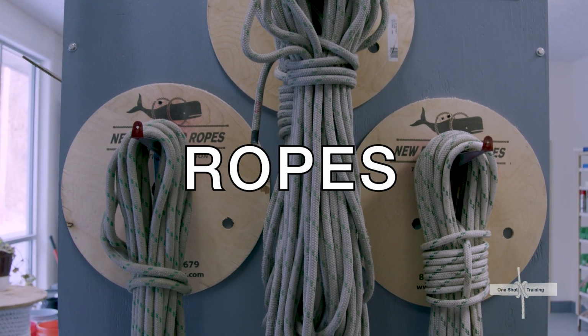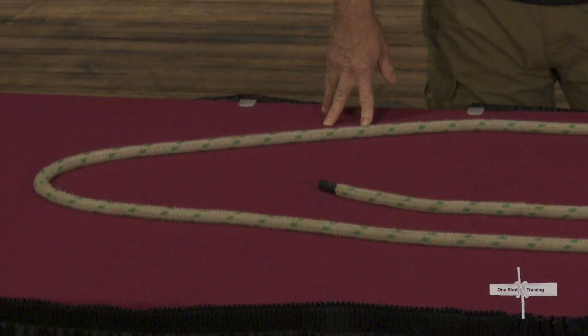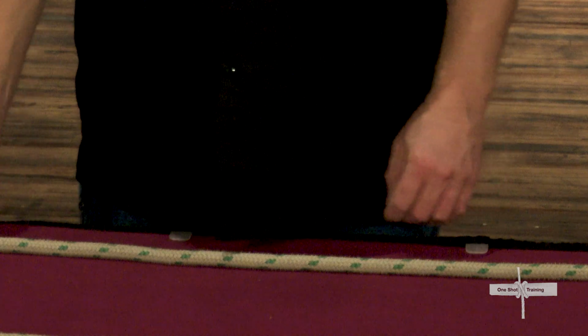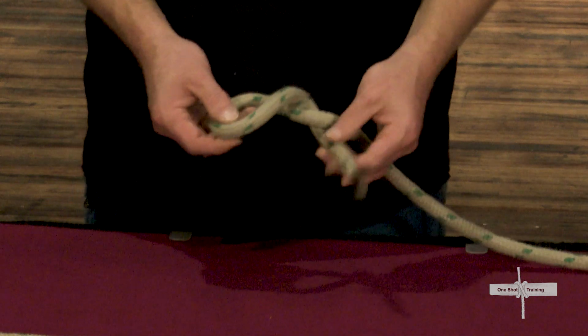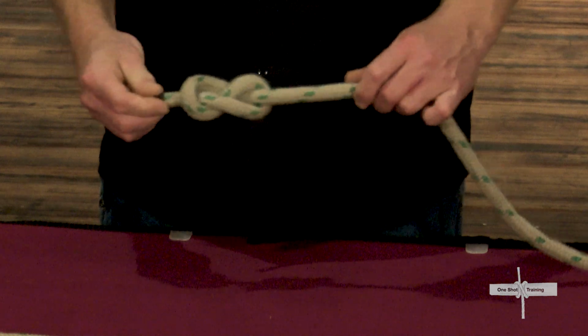We use many kinds of rope in the rigging system. Fiber rope may be made from a natural or synthetic material that is twisted, braided, or woven together. When we say fiber rope, we're talking about the kind of rope we commonly use to tie knots. There are different diameters, types, materials, and strengths of fiber rope, so ensure that you're actually using the right kind for the task you're doing.